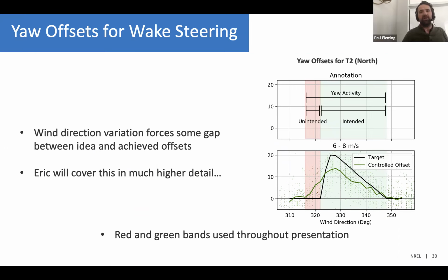So here you get a nice view of, as the data comes in, we have our confidence interval shrinking and the pattern of that area where we are operating wake steering, from just around the magenta dash line where the turbine is directly upstream from the other, and off to the right. So in between the magenta bands is where we were actively trying to do wake steering. You see those two lines come apart in a good way. And you see a gain in the energy production downstream.